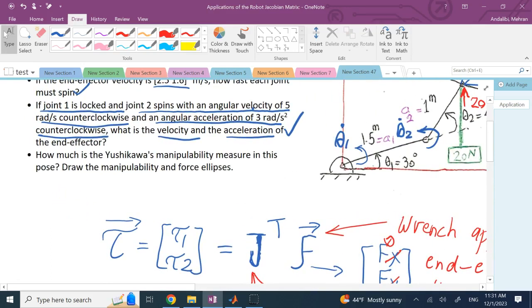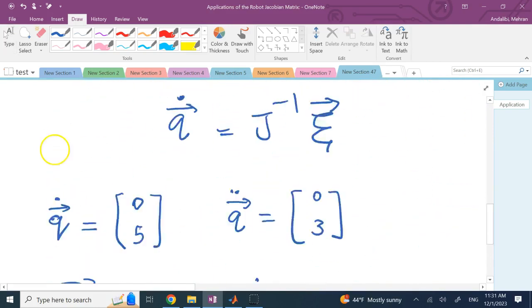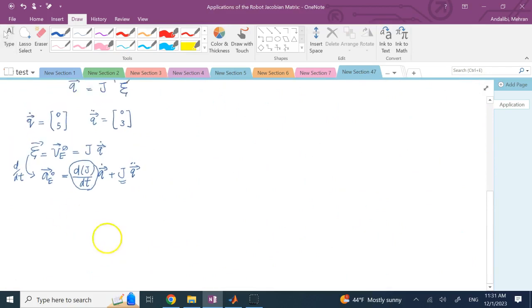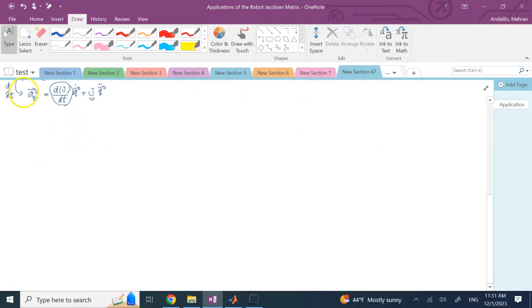Finally, manipulability, which is a measure of how close the robot pose is to a singularity. And one of them that I mentioned in my videos is called Yoshikawa's manipulability measure, right? And that's basically the product of the singular values of the matrix JJ transpose under a square root, which for a square Jacobian matrix, the Yoshikawa's measure mu is simply the absolute value of the determinant of j.